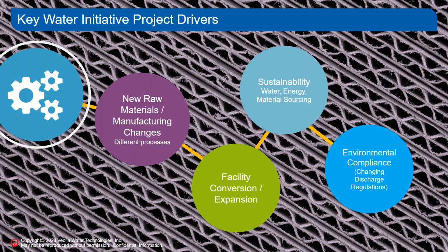Sustainability is at the forefront of the paper industry, so conservation of water resources is a key license to operate. It is expected by their customers. Water can be recycled from various places inside the mill, as well as from the final effluent back into the mill. The degree of closure of the water circuits depends on the type of mill process and the various costs of production. Some form of water treatment is likely to be required to enable water reuse to avoid issues related to final product quality.